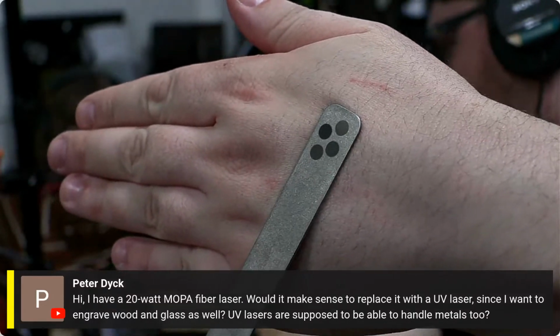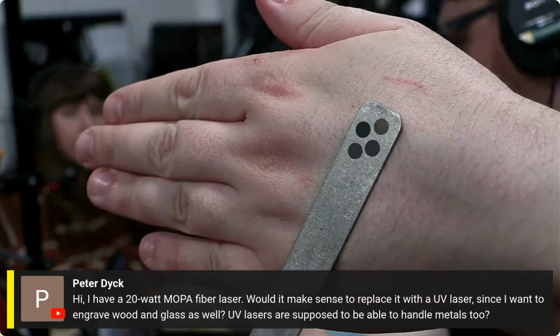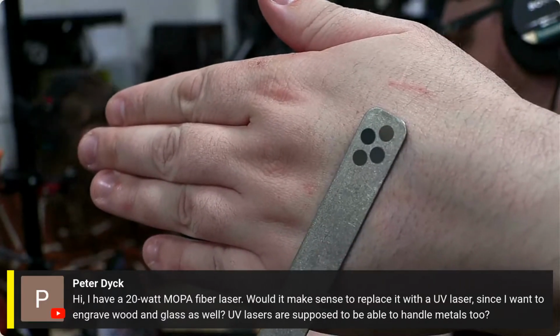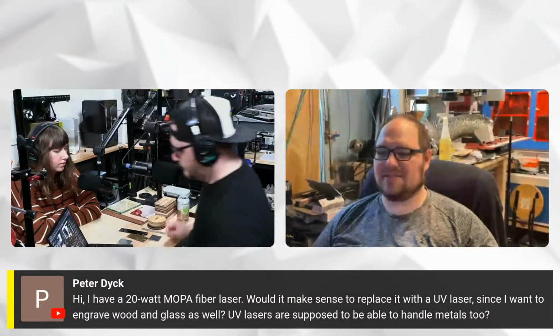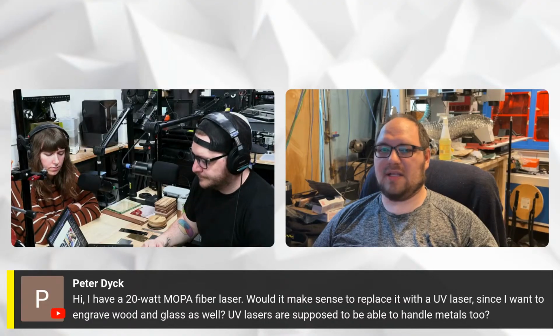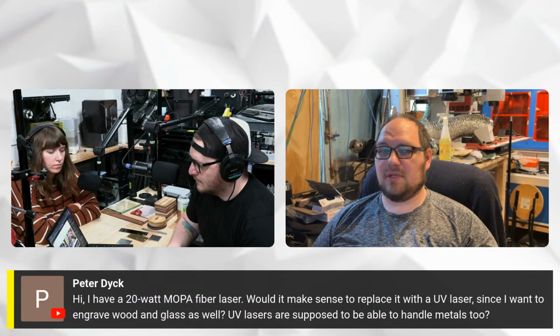But the long story short to your question, Peter, is it's not a replace thing. Each laser has things it's good at and bad at. Fiber is exceptional at metals in general, right? Particularly if you're going for colors, or if you're trying to engrave subsurface. UV is not generally amazing at getting below the surface of metal.